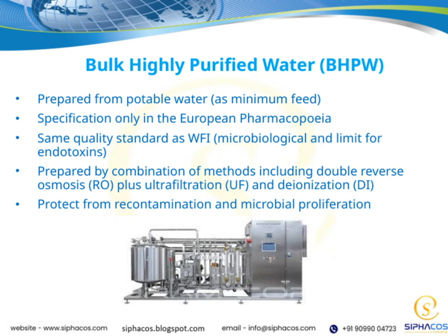This water is prepared starting from potable water, which means it meets basic drinking water standards, and then it undergoes additional purification to reach pharmaceutical quality. The specifications for BHPW are only defined in the European Pharmacopoeia, ensuring a consistent and recognized standard across the industry. Importantly, BHPW has the same high-quality standards as water for injection, or WFI, particularly when it comes to microbiological purity